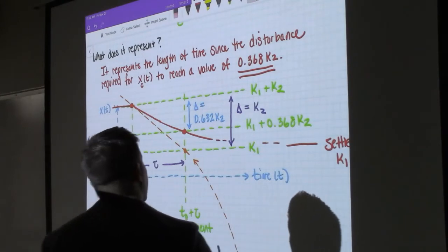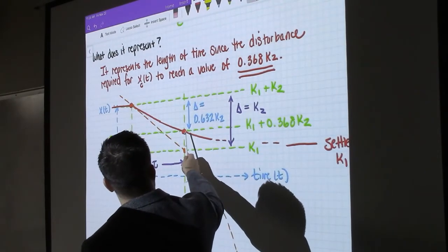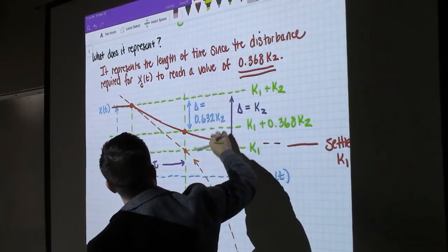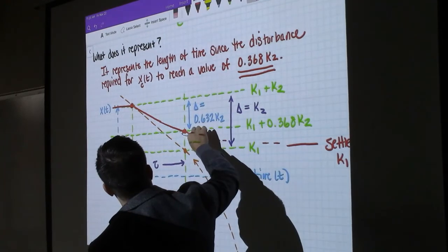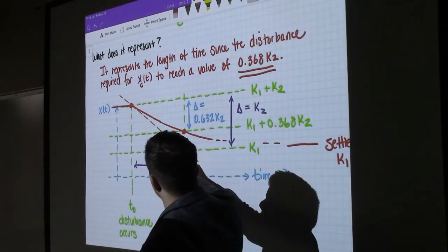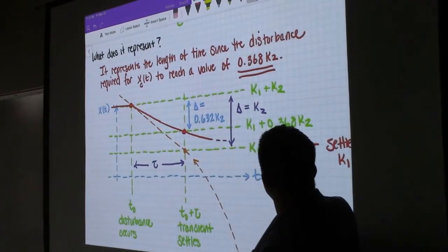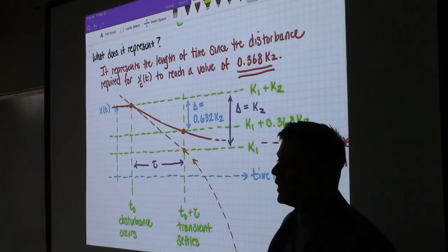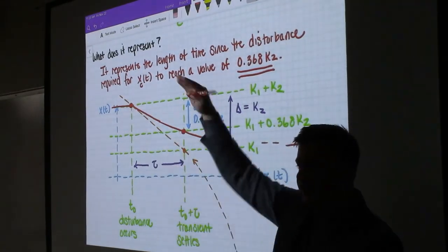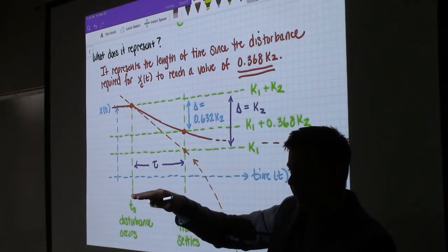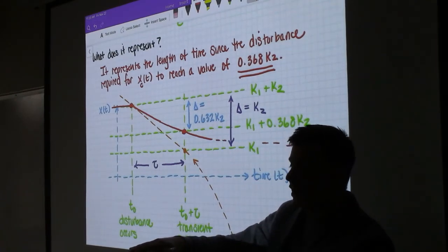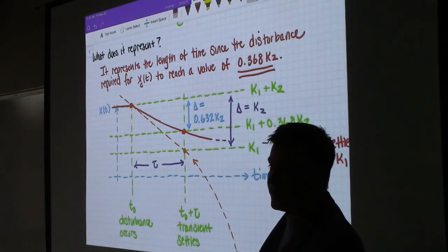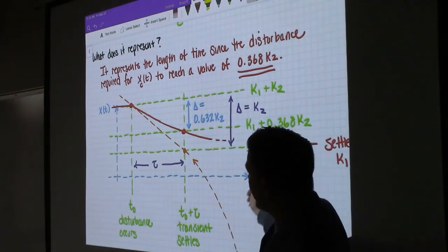And there is. It's mathematically defined. So if we have this right here as the total changing component of the transient, we call it settled, or the difference, so the value of x of t after tau seconds will be 36.8% of what it once was, or 63% settled. If you think about going from here to here, so it settles like this. This is 100%, this is 50% settled. And so somewhere right here is the point at which the intersection of tau occurs, when it's about 63% settled, or there's about 36% of the transient left to be settled. Okay, so we'll start with this next time.